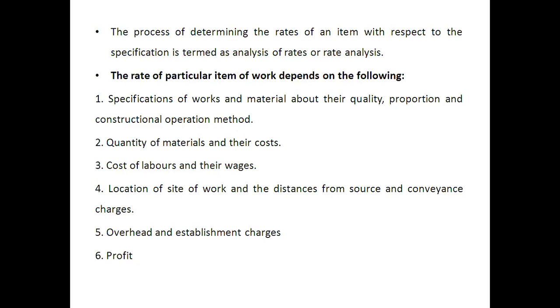From which distance I am going to handle my particular work is again important, because that will affect the rate. If the transportation distance is longer, then you require additional transportation charges, which will ultimately increase the cost of the project. Then overhead charges and establishment charges, then profit. These parameters will definitely play a major role in deciding the rate of a particular item of work.